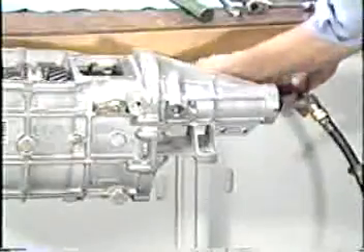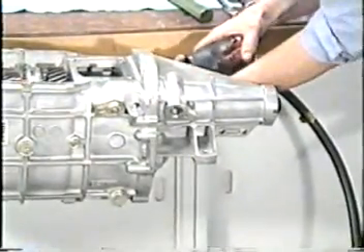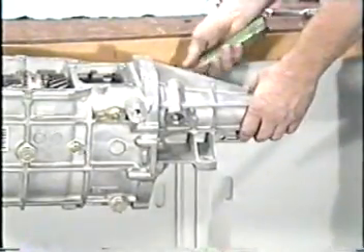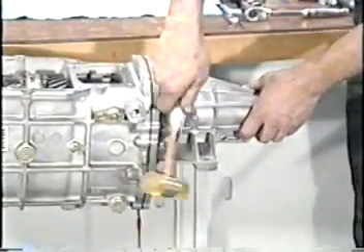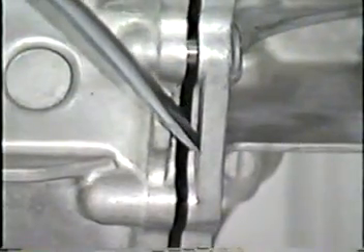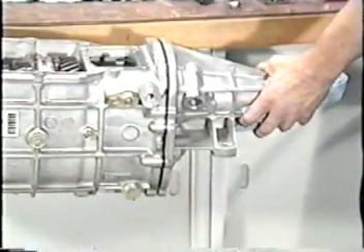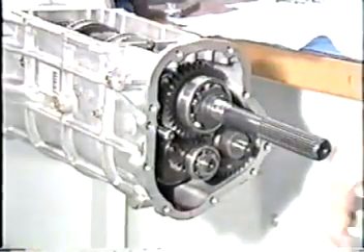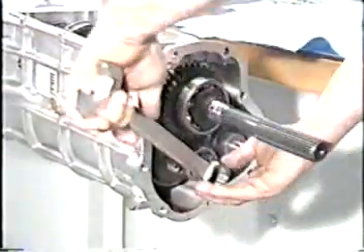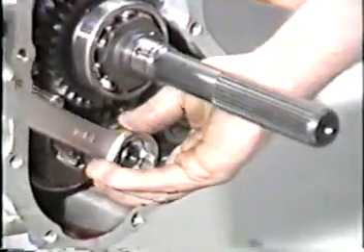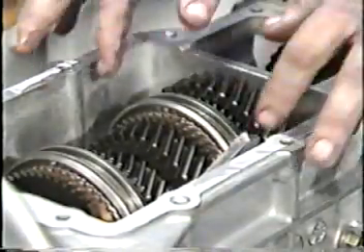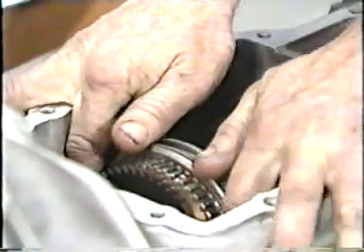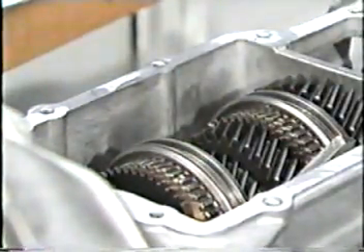Note that transmissions or transaxles with aluminum magnesium cases can be easily damaged by prying. Use a plastic-tipped mallet to loosen these cases instead. Pry carefully at the pry bosses to avoid damaging the mating surfaces, which can cause transmission leaks. When it's necessary to lock the transmission output shaft to keep it from rotating during removal of the lock nut, simply slide the 1-2 synchronizer and the 3-4 synchronizer onto the first and third gears.